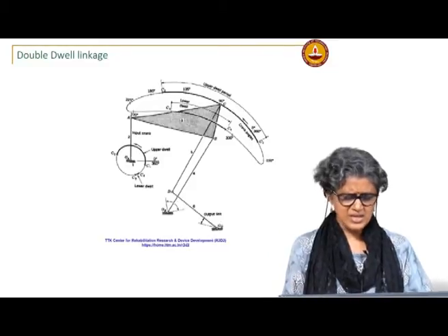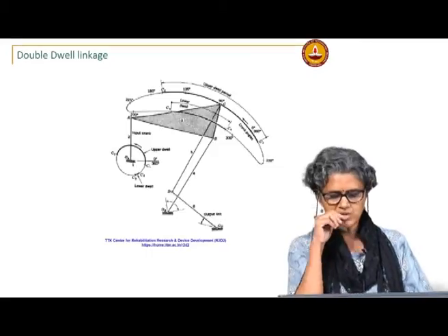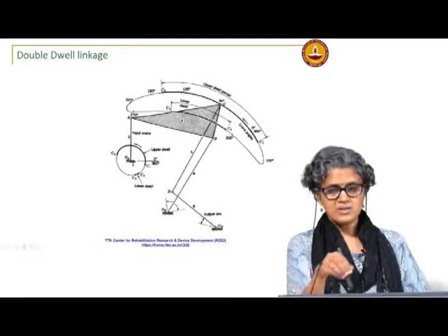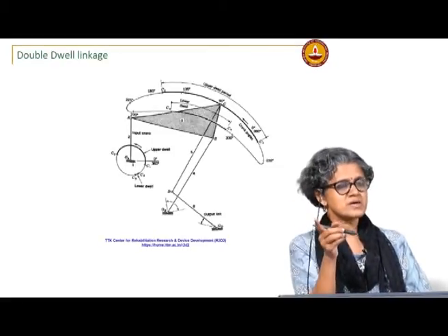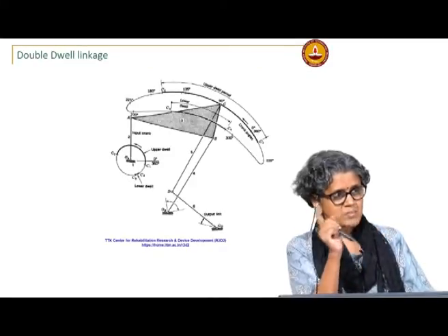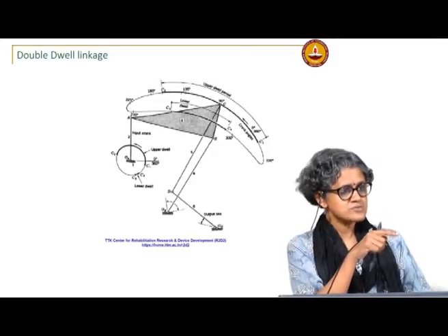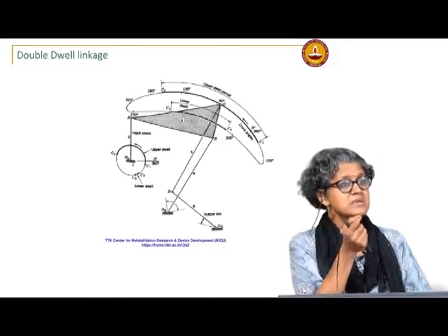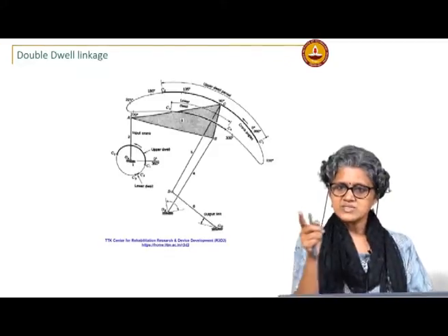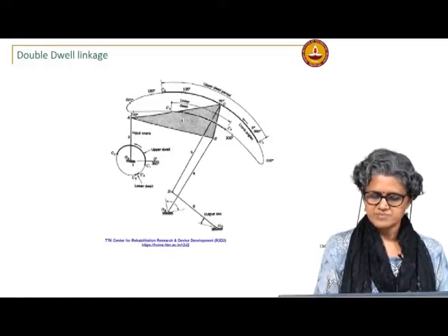So, this is another good example of using coupler curves. With precision point synthesis, I can specify points, but I can't really say how the linkage will behave as it moves between those precision points. Coupler curves give me a little more control over that, because the curve is a continuous curve. So, I have an idea of how that is going to be traversed.